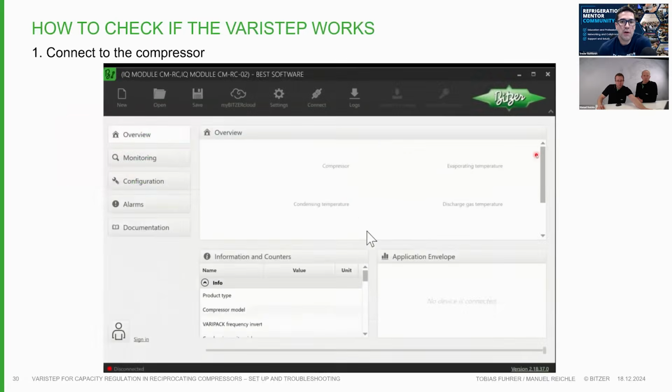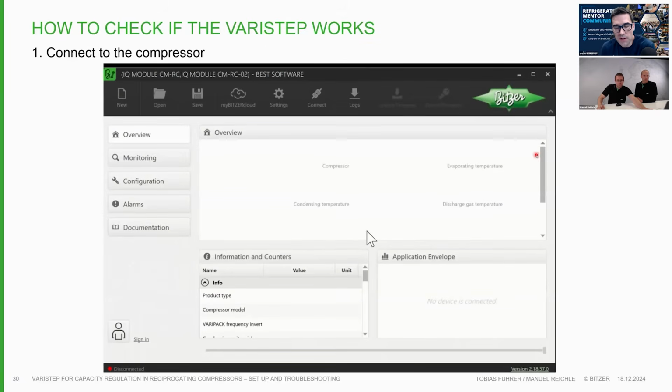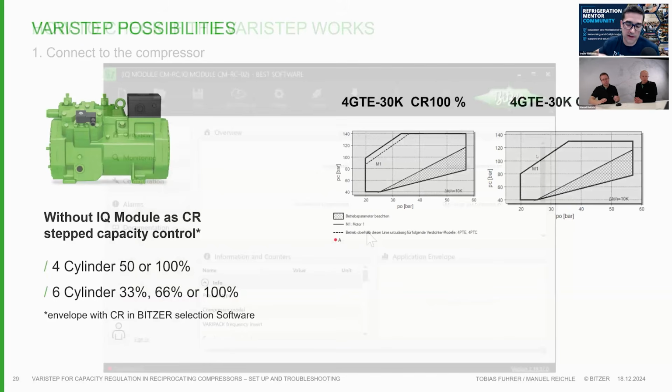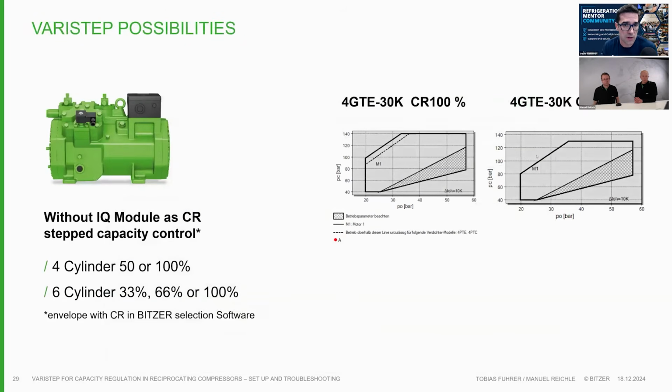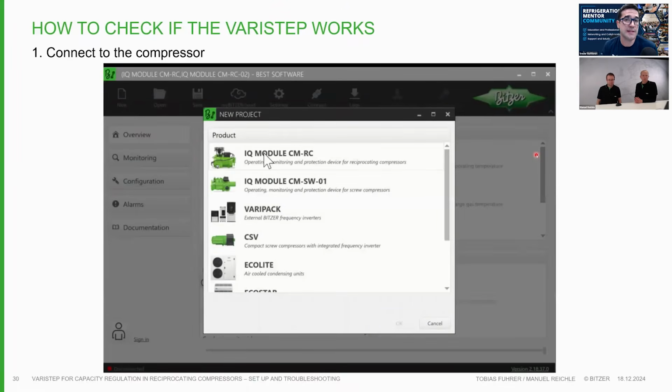And this is so important as a technician to understand, because a lot of people hear about operation envelopes and permissible area, but when you're in the field, you're not always looking it up. This is why I keep saying you got to go into that specific compressor, because they're showing multiple operation envelopes here for different compressors. They're going to have different envelopes, and you got to stay inside that.